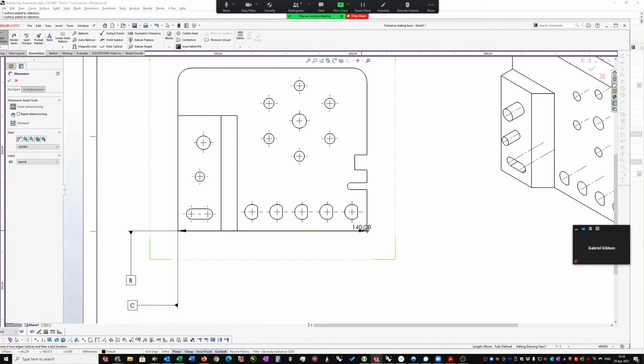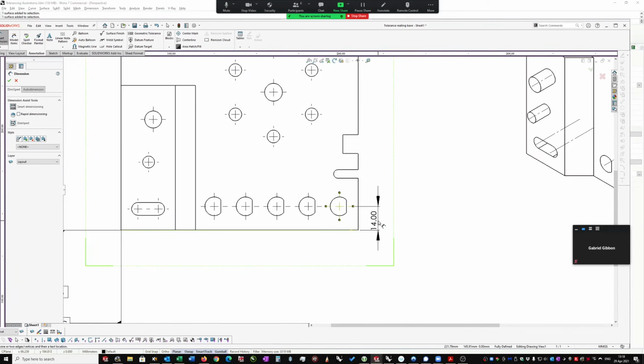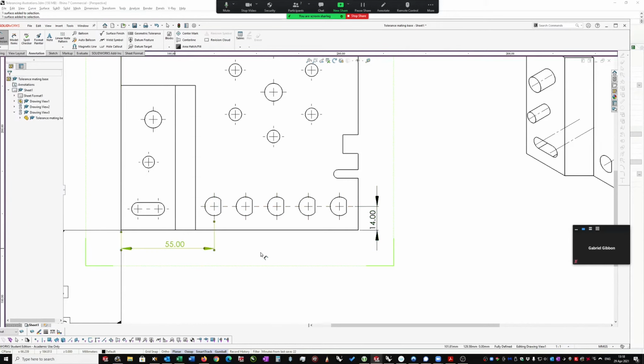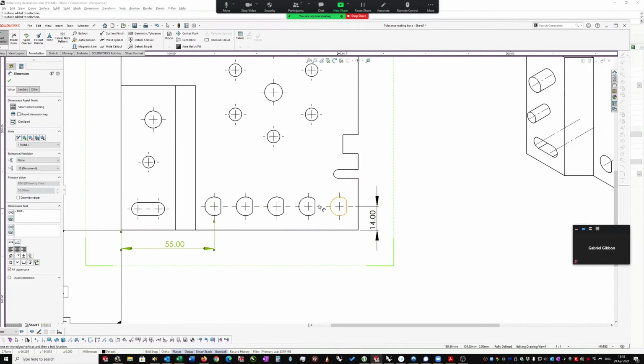So the first thing is I want to know what is the y dimension. That's 14. Okay. And I also now want to know where do I start this sequence. So that's going to be my z dimension or horizontal dimension. Okay, so now I can see what is clearly a line of the same sized item. Now all I need to do is put in what the regular spacing is here, and that's called pitch. So I take one more dimension from here to here.